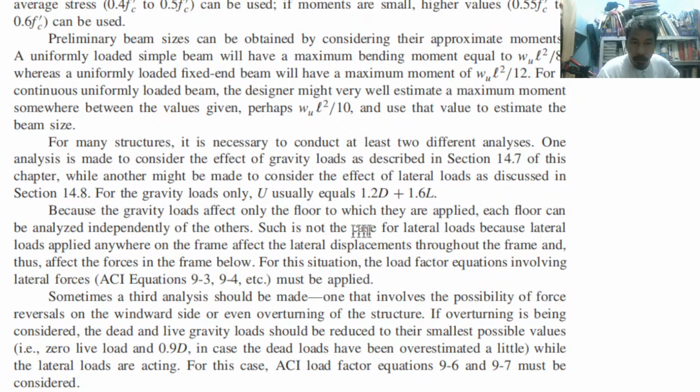Because the gravity loads affect only the floor to which they are applied, each floor can be analyzed independently of others. Such is not the case for lateral loads, because lateral loads applied anywhere on the frame affect the lateral displacement throughout the frame and thus affect the forces in the frame below.